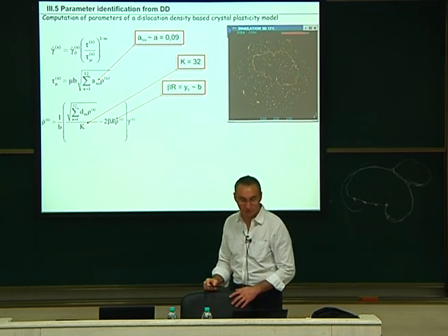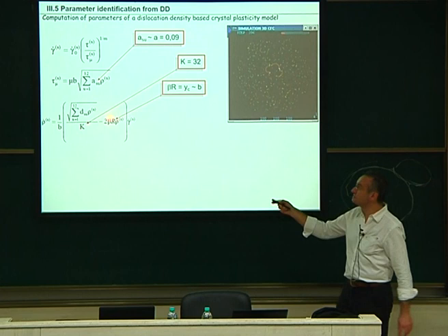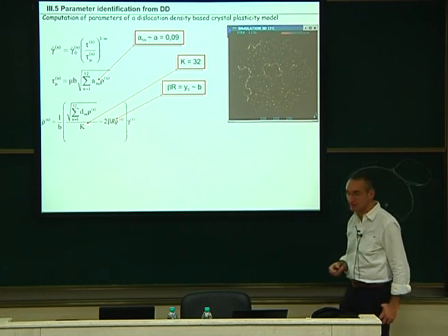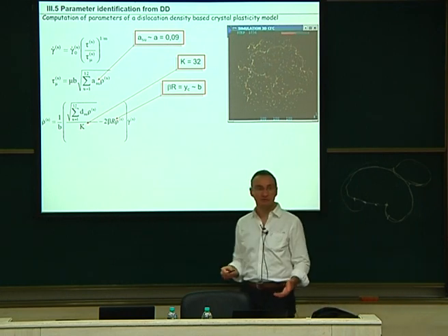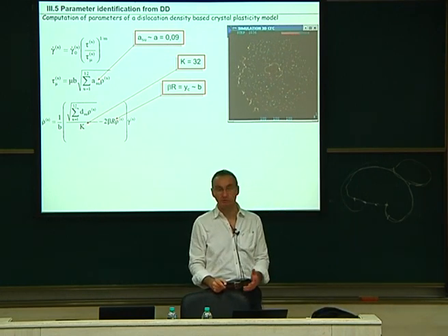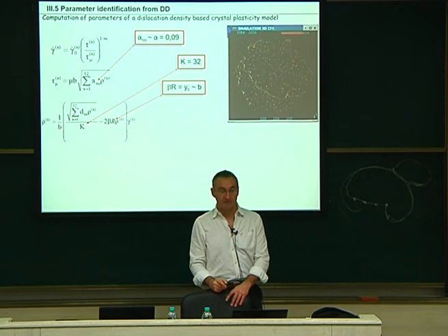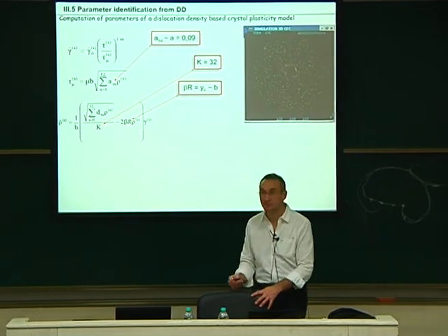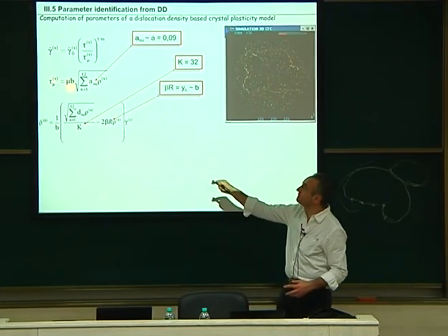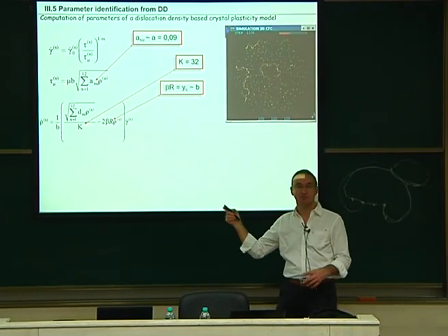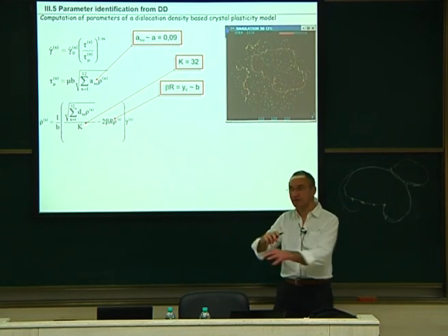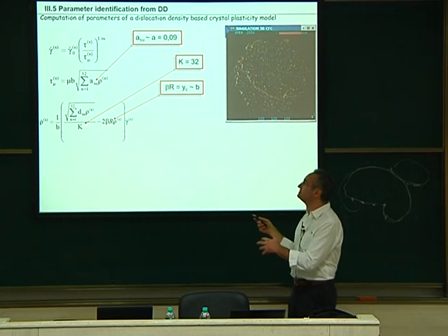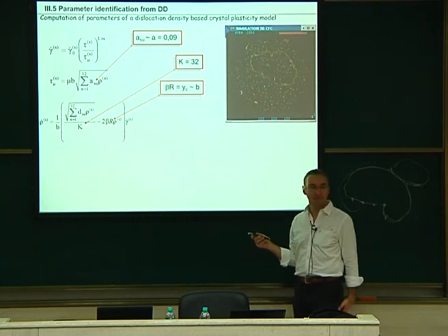You can also compute the annihilation distance, the radius at which two dislocations will be totally annihilated, which is a Burgers vector, like that. So these are easy parameters that we can compute using DD. They are very hard to measure experimentally, because experimentally it's impossible to measure the strength of the systems with another systems. You always have all the systems together. You cannot isolate one or two and make an average. It's impossible. So this is where I would say DD is a very nice tool.